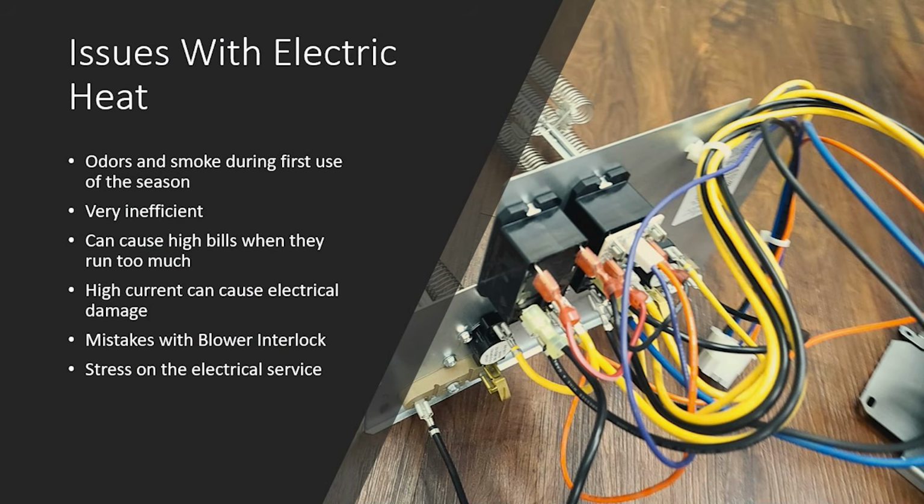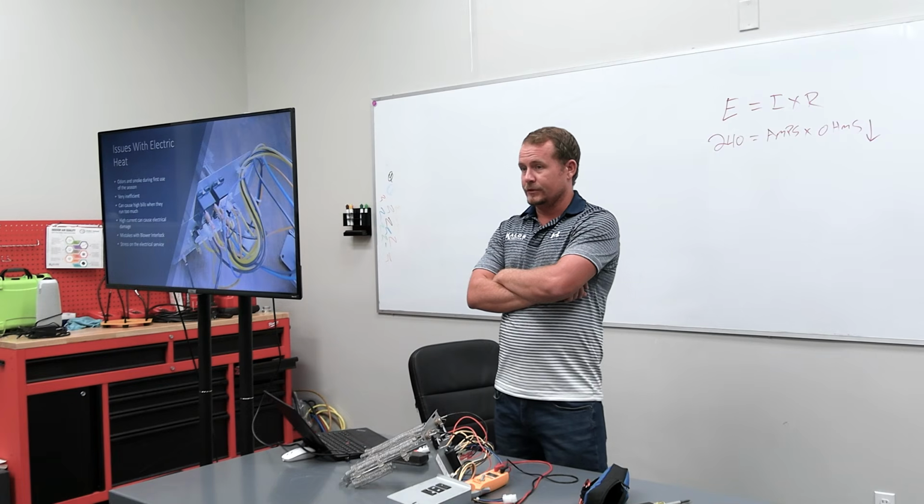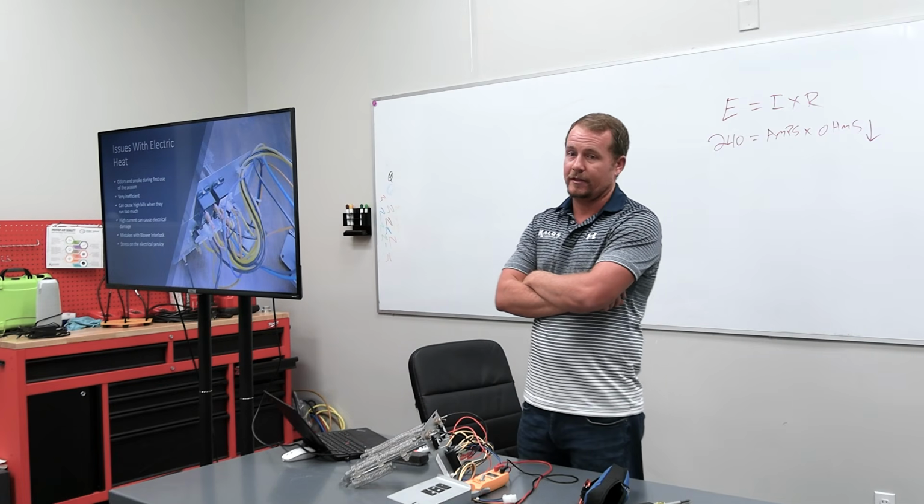What's the bad news? Well, one of the biggest things, and this is the main thing I want you to take away from this, when we work in a market, which we do, where we have a lot of electric heat strips, we need to make sure that we burn them off. We need to test them at least once a year. And we need to let the customer know that there's going to be some odors, maybe even some smoke in extreme cases, if it hasn't run in a really long time, when we first test them. So that is an indication to the customer that we've done our maintenance.